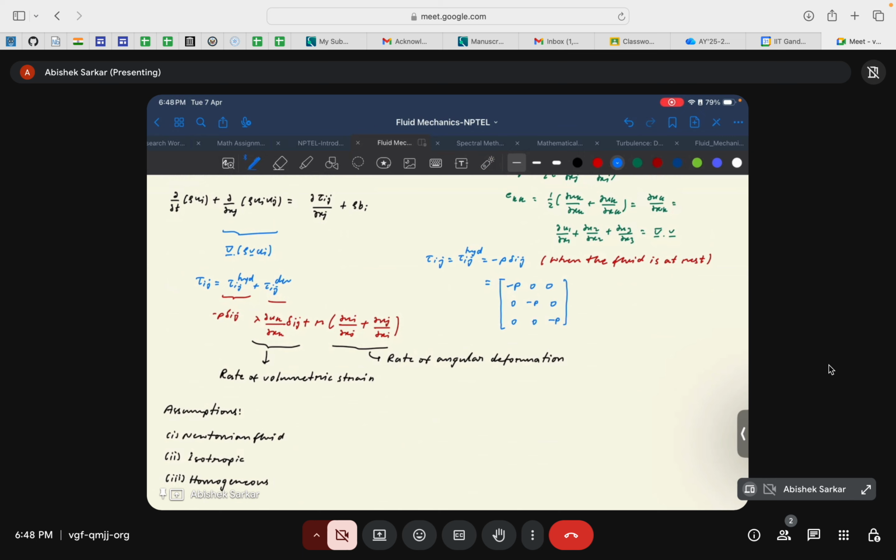In that case again it's generating a compressive action, although in general it is causing the enlargement or expansion of the pressure vessel. But at that particular point inside the pressure vessel where the pressure is acting, it inherently acts as a compressive force. That's why the negative sign. To understand it better, you need to be able to visualize that idea, but it is consistent with that understanding.